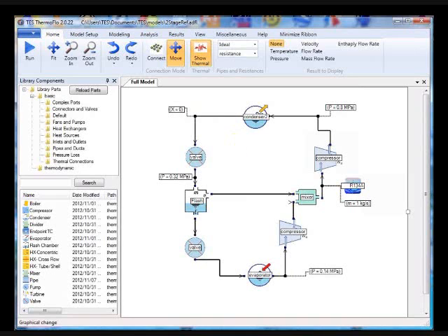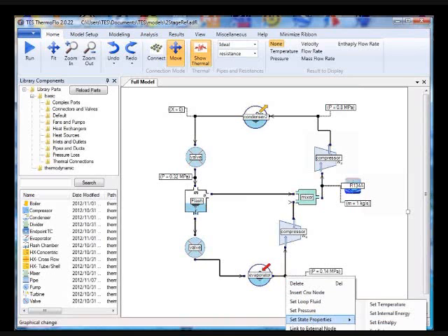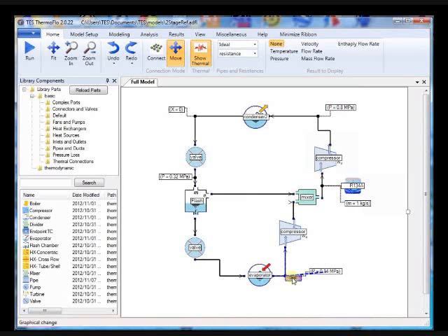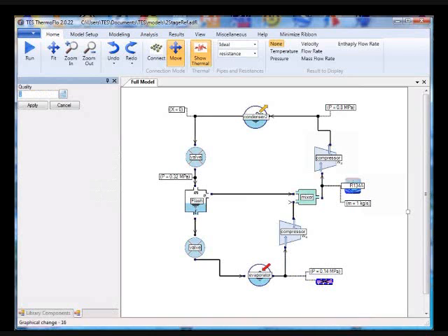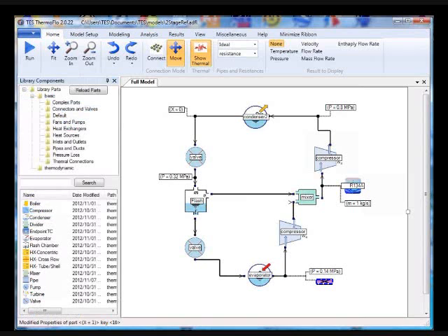Also at the bottom, we have an evaporator. If it's ideal, it's going to come out as a saturated vapor. So we go there and set that quality equal to 1. That's about all you need to do. You can solve the problem. No need to look up steam tables, refrigerant tables, and iterations and all that.